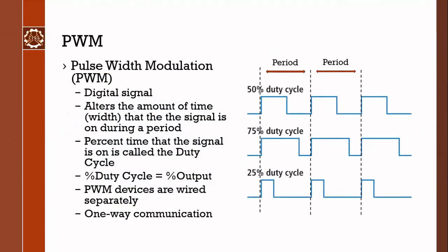All right, so you guys heard Devesh mention a couple words fast there. You heard CAN and PWM. These two are basically the ways that we deliver signals from the RoboRIO, which is the brains and the processor, out to the various devices that it controls. CAN and PWM are the two possible ways to do that. Back in the day, PWM was the only option and it's what we used exclusively. PWM is still the thing you're going to see, like on the VEX controllers. It has a really iconic red, black, and white 3-wire cable that you guys have definitely all seen.